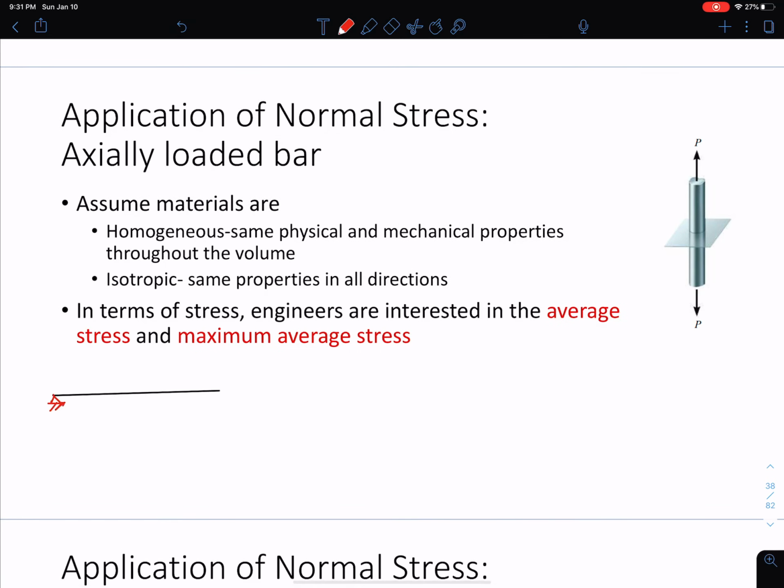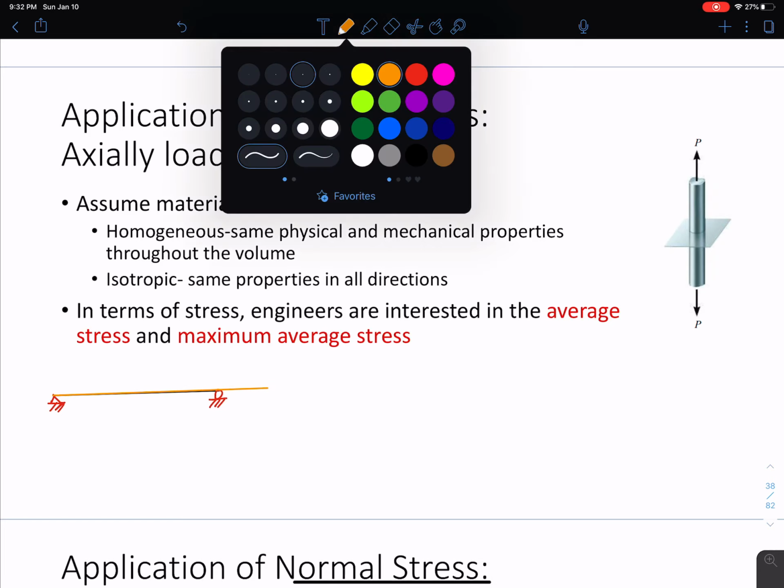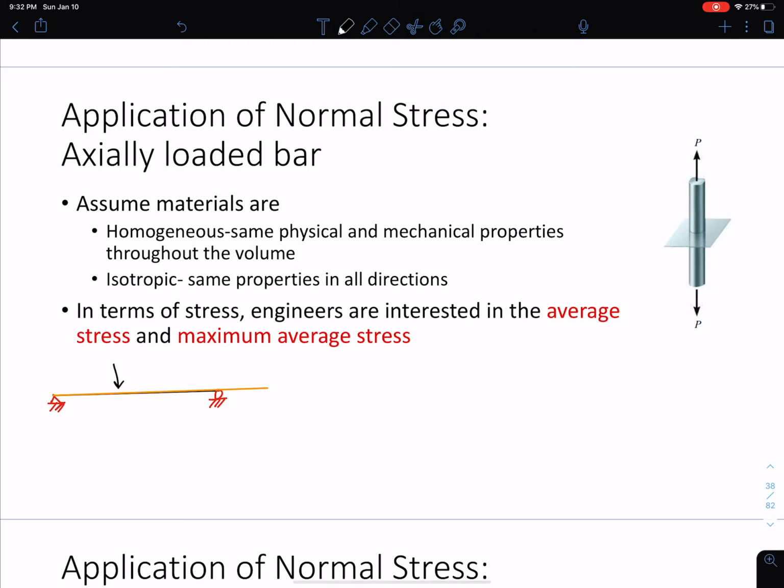So a beam, I've mentioned this a couple times now, is generally defined as a long, slender member that is loaded perpendicular to its longitudinal axis. So you can see here, the longitudinal axis is this axis right here, right? And it's loaded perpendicular to that. So we're typically talking about gravity loads. These are loads due to gravity. You can think of beams in a building. If you walk into a parking garage, you look up, you'll see a lot of concrete beams holding up the floor above or the roof above. Those are beams, and they're typically holding gravity loads, okay?